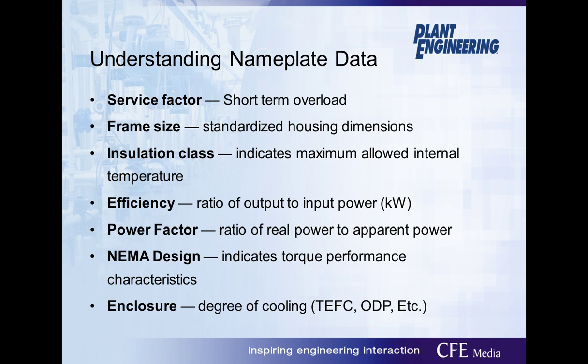If your motor is on an application where the torque fluctuates, it is always a good idea to have a motor with a higher service factor. This will allow the motor to withstand a period of time where the motor can be overloaded by the service factor multiplier. This meaning, if the motor has a service factor of 1.25, the motor can run at 125% of rated load. While keeping in mind that overloading factors lead to higher currents, which in turn leads to higher motor temperature. Always monitor the motor temperature closely to eliminate any chance of shortening the life of the motor.